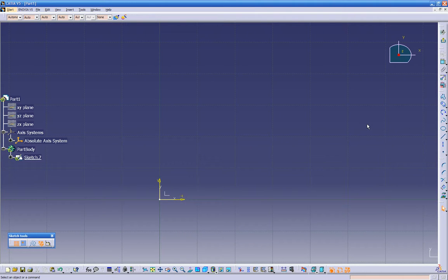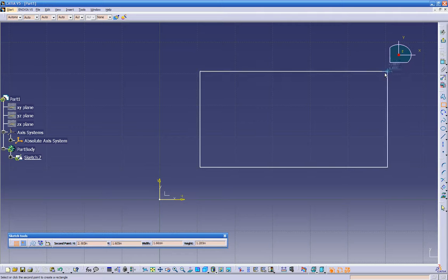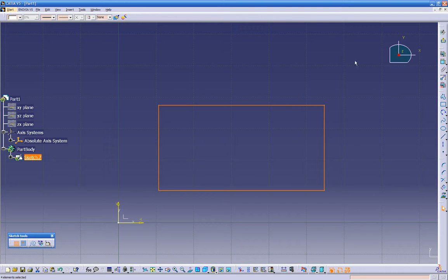And let's create another rectangle. Let's go here. And this time I want to show you something more advanced. Let's unclick this option right here, the geometrical constraints, and I'll show you what this does. So let's create a rectangle. Okay, hit the screen, and let's put some dimensions on it.